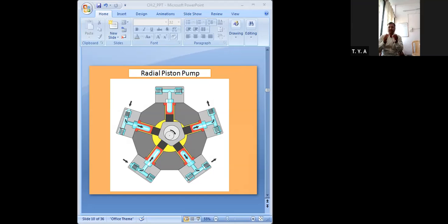The fluid starts to come inside, that means inflow, and it happens in these two pistons, you can see its direction. And outflow will happen at these two pistons. That is controlled through the revolving ports.